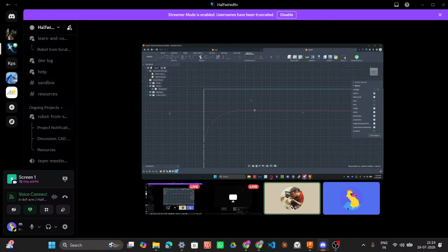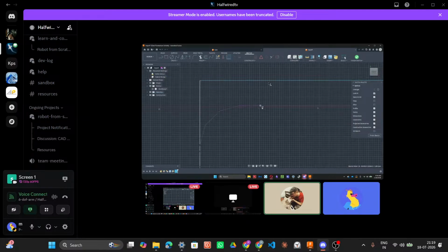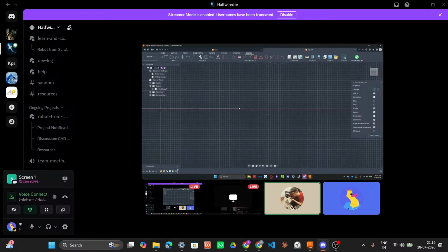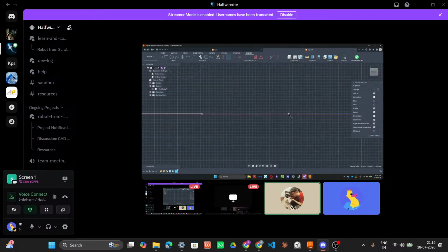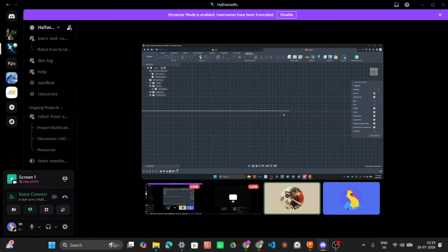So it means that basically this point, if I say it's coincident with this line, it has to land on this line somewhere. But right now this point is still not constrained, so I can change the distance. But if I said it was coincident with this point, then now it can't move because it's stuck to there.